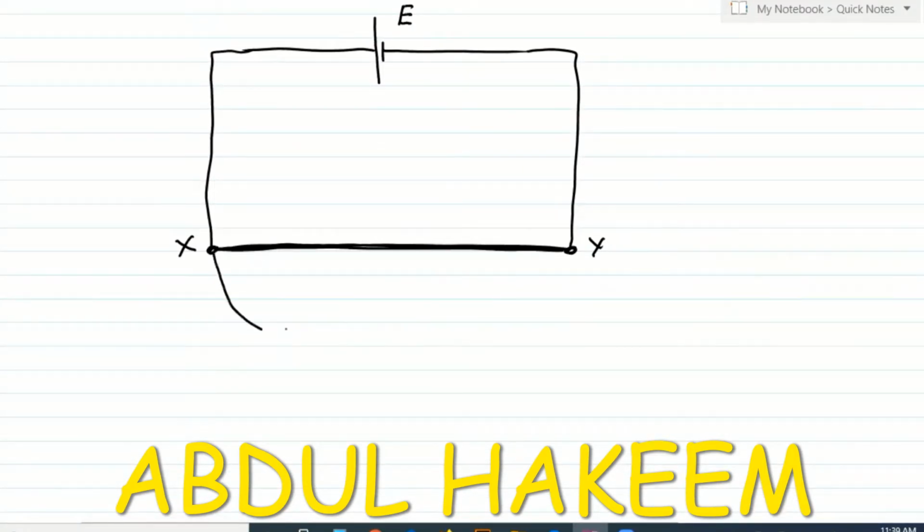That unknown cell must be connected in parallel to the first, meaning the positive side of the unknown cell must be connected with the positive side of the known cell, and no voltmeter. You can add here any galvanometer or ammeter, and then this movable contact M.